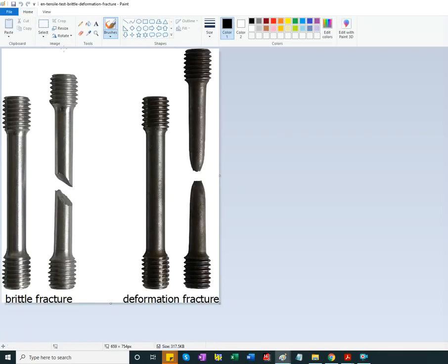So this was a tensile test, and fracture occurred at 45 degrees. That corresponds to the maximum shear stress element orientation. So the longitudinal direction is a principal axis, also called so. We have maximum tensile stress, and zero normal stress on the other element.